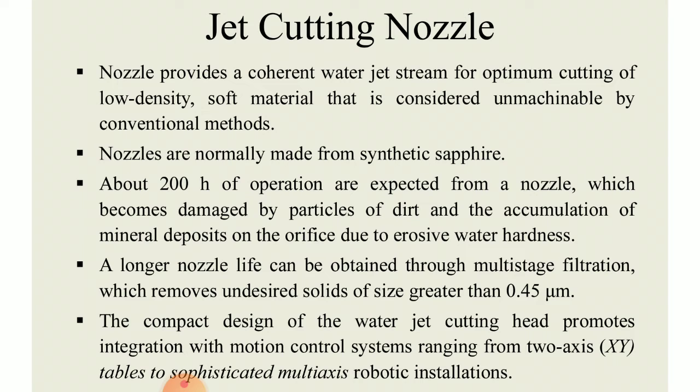Right? Generally, if filtration doesn't happen successfully, even a single particle of dust and dirt may damage the nozzle. A longer nozzle life can be obtained through multi-stage filtration, which removes the undesired solids of size greater than 0.45 micrometer.